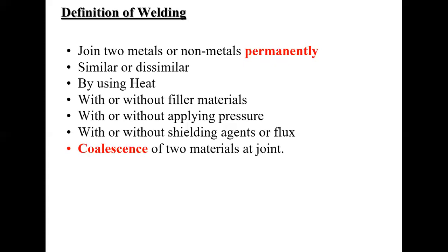So if we want to remove the oxide layer from the metals, we have to use this flux, because without removing this oxide layer with the help of flux, we cannot get the fresh metal contact. And if we don't get the fresh metal contact, we cannot join the base metals as well. So this is one application of the flux. There are other applications too. I will discuss this flux in detail in my upcoming videos.